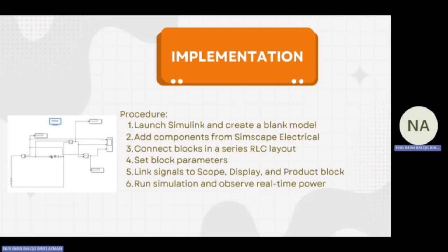We observe real-time voltage, current, and power waveforms in the scope and the power values in the display. We also tested variations by changing component values to simulate RL, RC, or R-only circuits, which help us study both transient and steady-state responses.